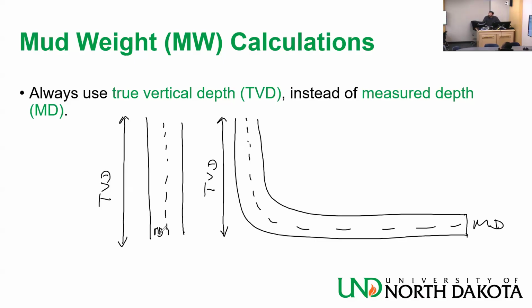And when it comes to rho g h, which was absolutely correct, what we are using for the hydrostatic pressure, it's the true vertical depth that matters. Because if both wells are filled with the same density of fluid, they would both have the same bottom hole pressure. It doesn't matter that one is longer than the other. Now, if there is motion, there are friction losses associated, and one well is longer than the other, so it would have bigger friction losses. That would be a different story.